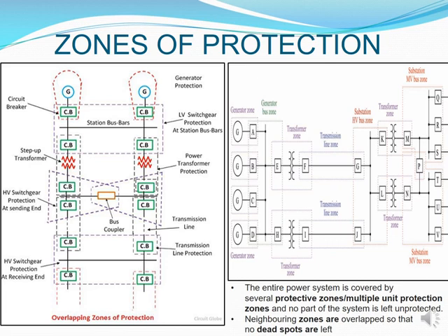And the nice thing about this system is that if only one of those transformers is isolated, then the other transformer can be utilized to feed into the rest of your system. In other words, the bus coupler at the bottom of where these transformers are will be closed, so that we can be sure that your left hand side or your right hand side, depending on which transformer is faulted out, can have supply continuity going out onto them.